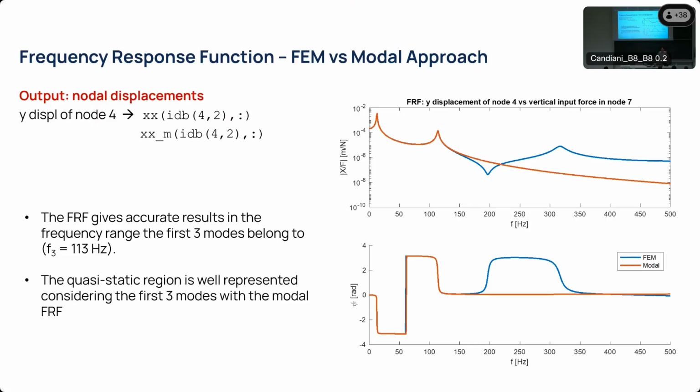Of course, you can play with this, and I would suggest you try to see the behavior of the structure while changing the number of mode shapes you insert. Let's try using only the first, the second, the first and the second, all of them, and try to feel the differences, try seeing the effect on the amplitude and the phase in various points where you change how you want to reconstruct your structure. Because in some frequencies, as you can see, below a certain threshold, the reconstruction is perfect, but at higher frequencies, it changes a lot.